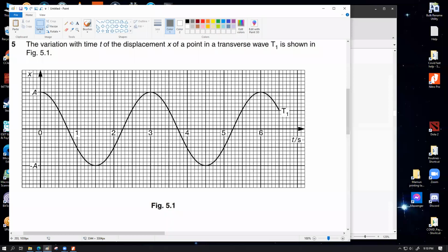Now lagging means we have to replace all of the crests and all of the troughs, and the entire wave has to be shifted to the right by the relevant amount of 60 degree equivalent of phase angle. Now this horizontal scale you can see over here is actually the timing axis, and you don't have to bother about that as long as you can count the divisions. So remember that. Let me write this first for you. The way we know this thing is that 1 lambda is relevant to 360 degree is relevant to 1 time period, which for this question is relevant to how many divisions?